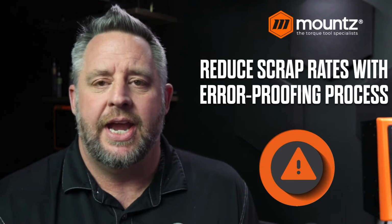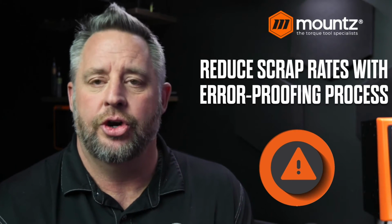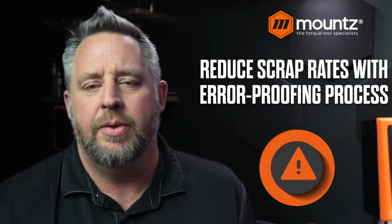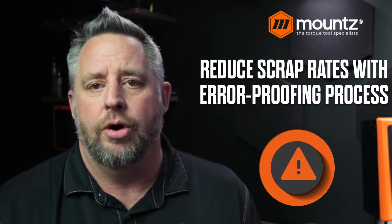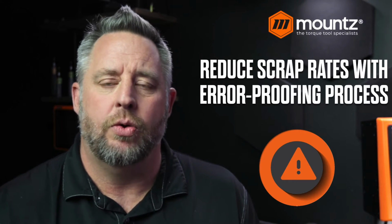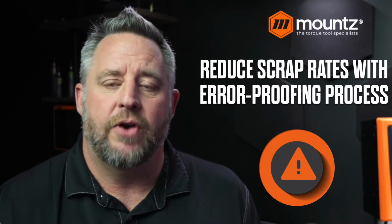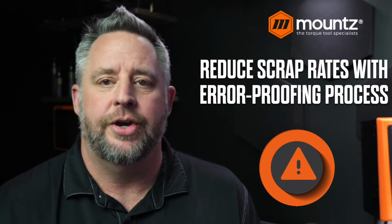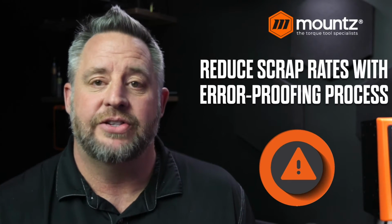And so we can create an angle or turn amount window. If we see common fastening errors like cross-threading or possible stripping or camming out of the bit from the fastener, these are all items that we can detect by monitoring the amount of turn or angle that happens within the fastening process.